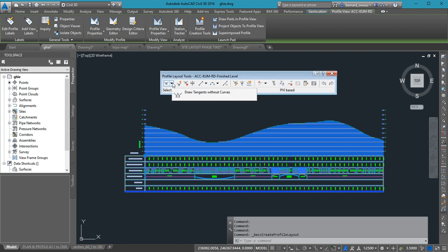In the lazy man approach, we are going to specify the minimum curve value, in terms of the K, it should use for sag and for crest. You understand? And all that we need to do is just draw the tangent, and it will be inserting the curves for us. The serious man will do it manually. He will put in the tangents or the grades and later come and put in the curves. But the choice is yours. As a beginner, let's use this one. But I don't use this one. I use the serious man approach. So let's try the lazy man approach.